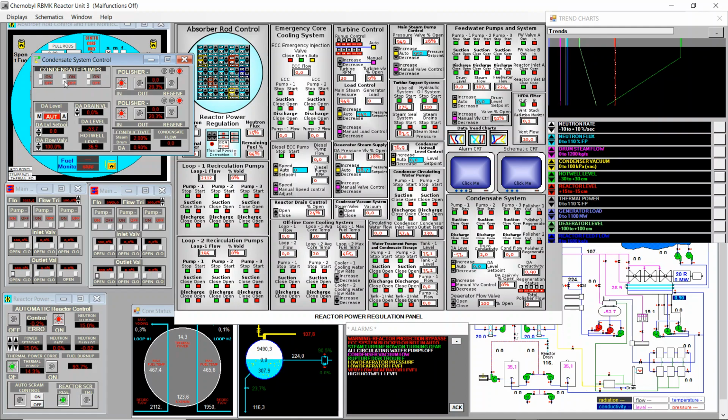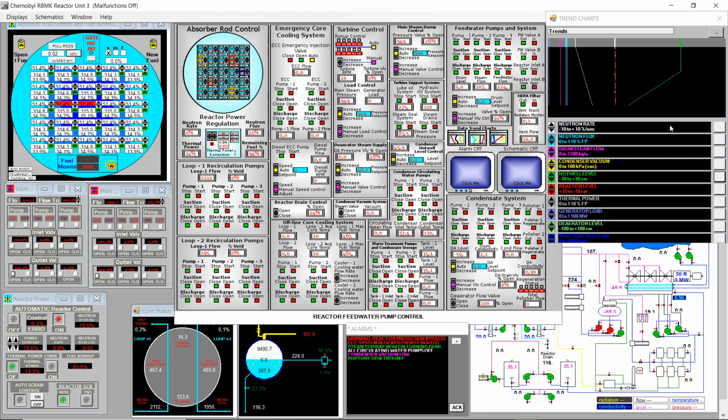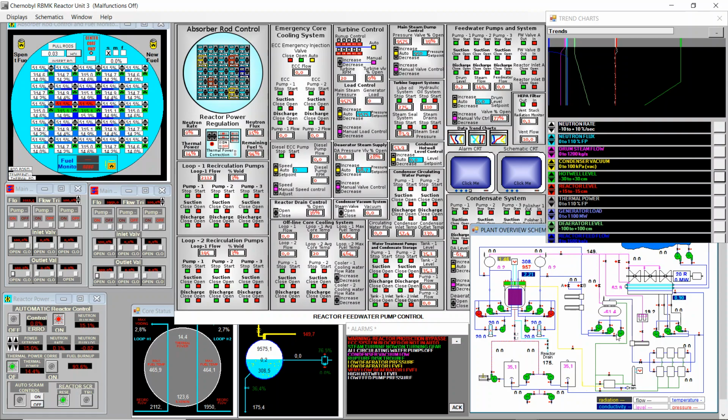The pump trip, that's correct. I will turn off the polishers anyway. There is no flow through them. Okay. We got some alarms. Very low deaerator level. And now we got the trip. We have the feed water pump trip, and this means now the reactor level will start decreasing. We see some small fluctuation here in the reactor level and also in the reactor activity.